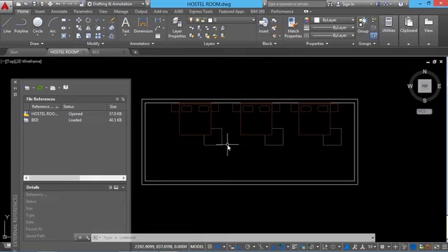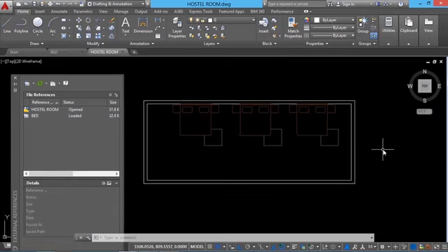That is the advantage. Here the parent of this Xref is the external drawing and the block definition is not created. The speciality of an external reference when you compare with block reference is that the external referenced file, for example, this particular drawing of the bed can be anywhere. Presently, it is kept in the local hard disk of this computer, but this file can be anywhere in a computer networked environment.